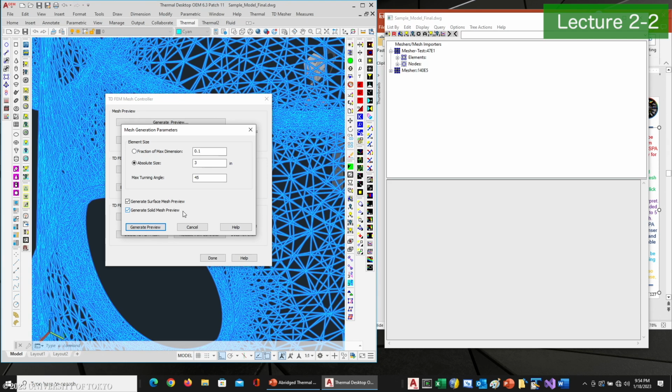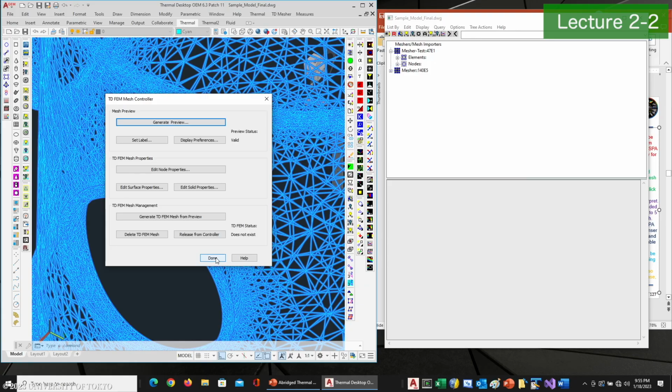By and large, I found, for my purposes, that auto meshers just create too many elements to be appropriate for most thermal models. I would never want to send that to somebody and say, yeah, let's run that, from a radiative point of view. It's just too detailed for the purposes that you need for thermal. So I am very much a proponent of building and controlling your meshes by hand to be an appropriate level of granularity for thermal analyses. But, to each their own. All right, so that's it on the mesh controllers.